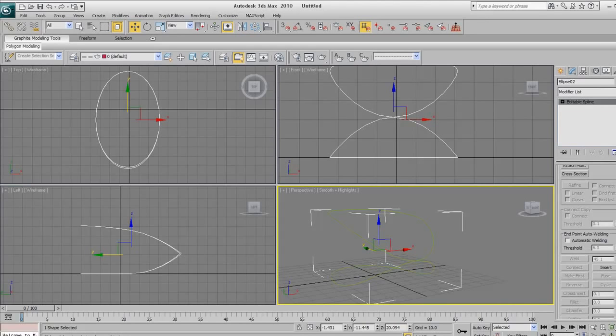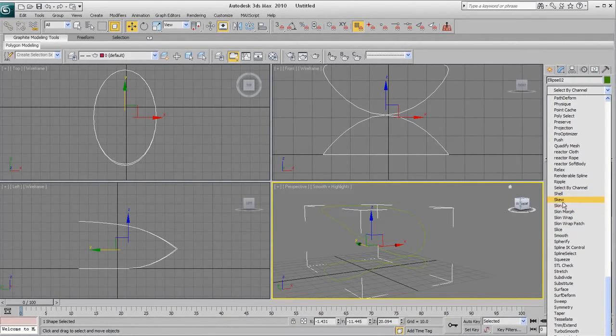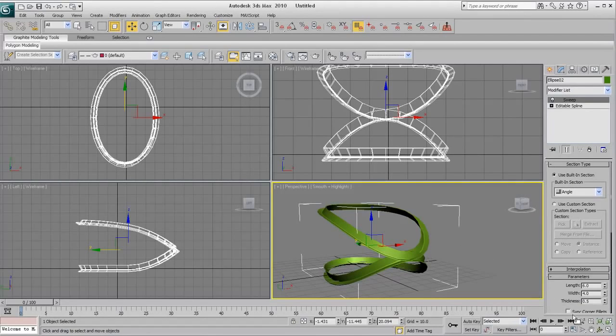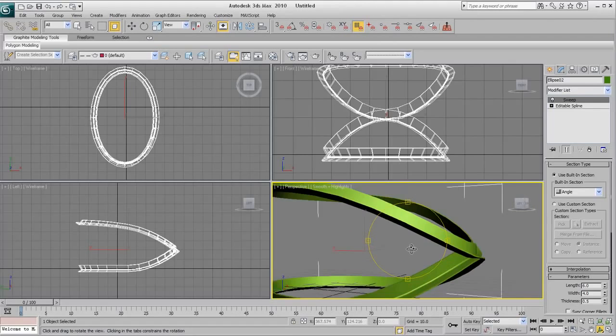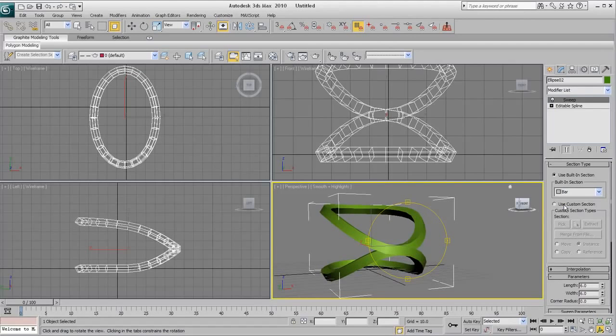Now let's do the same thing with the above vertices. Just click and drag so that you select both of them at the same time and then hit weld again. And now we have the same thing happen to this one. So if you click on that, and so we've connected them. Now we're going to align them properly. Go ahead and select the bottom one, bring it slightly higher and put this at the same place. But we don't want them to look awkward when we apply other modifiers. So go over to your top viewport and just move this back slightly, maybe up to there. You'll notice the difference on your left and top viewport.